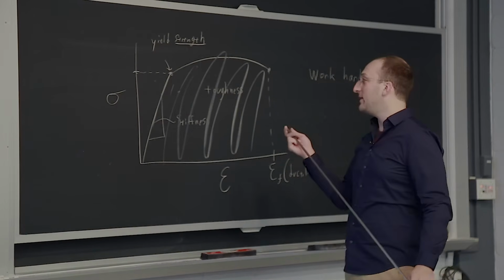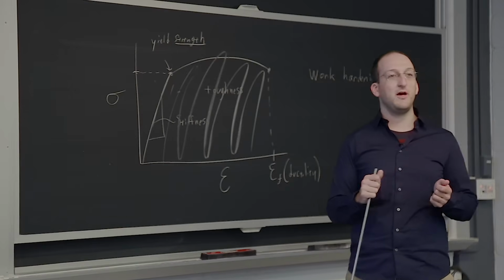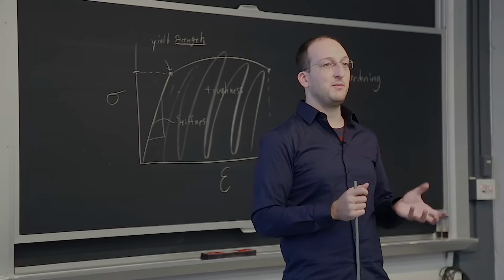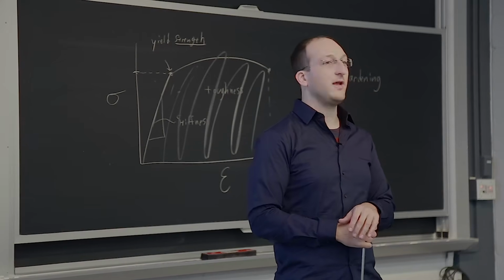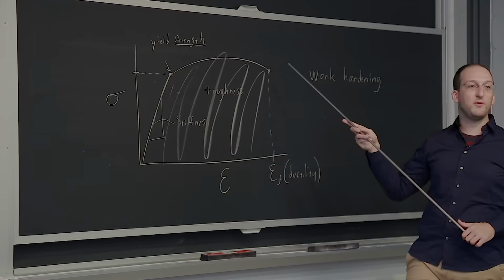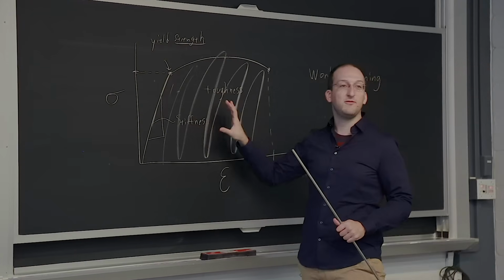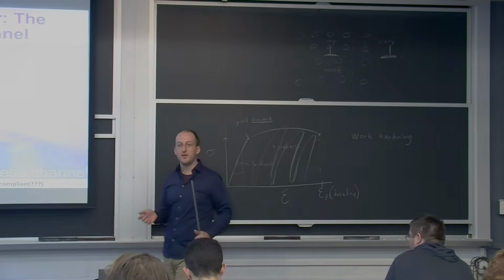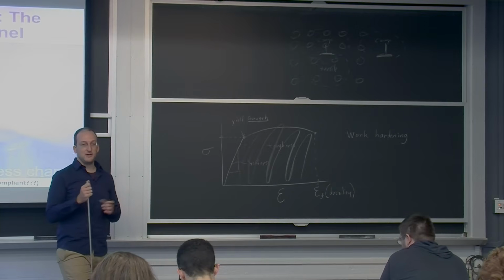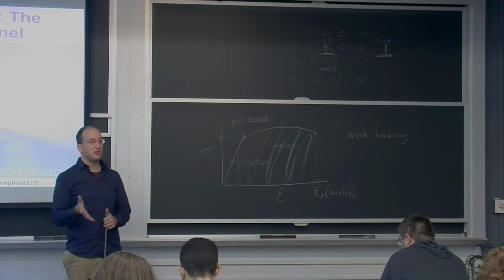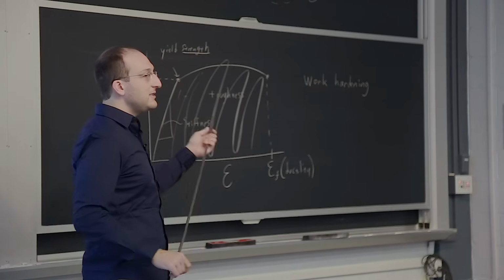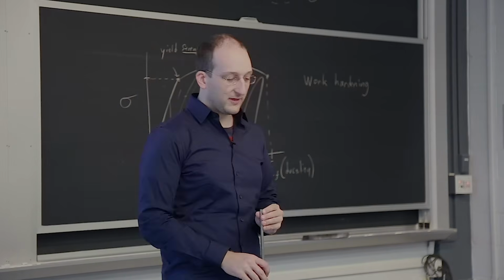So I would not call lead a very tough material because you didn't have to put a lot of energy into it. But did it deform quite a bit before you snapped it, or did it just crumble apart? Deformed a bit. Okay, so in that case, I would call it ductile because it deformed a lot before breaking, but I would not call it tough because it took very little energy to get it to that breaking point. And it wasn't that stiff because it was quite easy to get it. Let's say it's the amount of stress you put in versus the strain could be quite low. And it would not be very strong because it didn't take a lot of energy or stress to get it moving.